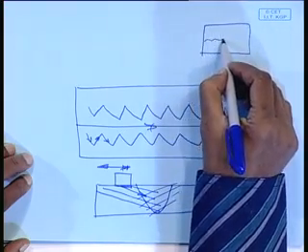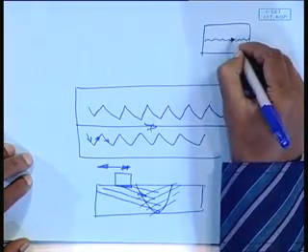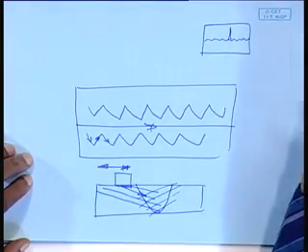So, any discontinuity it meets within the weld zone, in the form of a crack or a slag inclusion or porosity, will be reflected in the monitor, because otherwise the monitor signal will be something uniform. Wherever there is some discontinuity, there will be a spike.